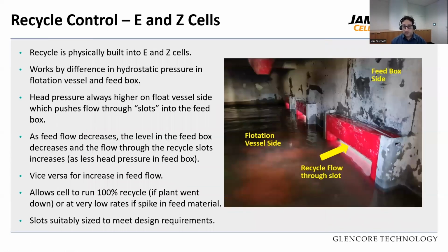The recycle is physically built into the E and Z cells. There's nothing fancy that has to be done, and like I said, it works on hydraulics and hydrostatic pressure in the flotation vessel. The head pressure will always be higher on the float vessel side, which will push slurry through those slots, and we control and size them specifically for every application. As your feed flow decreases, the level in the feed box will decrease, and through the recycle slots there's more head pushing it through, and this maintains your level.